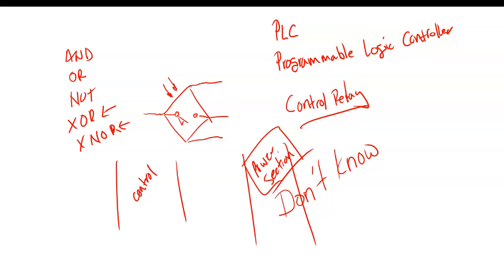one thing that 70E has established is what voltage is considered lethal. And what voltage is that? 50 volts. So anything below 50 volts is considered to be not lethal. Does that mean it won't kill you? No, it just means it's not considered lethal. Anything above 50 volts is considered to be lethal, and that's where all